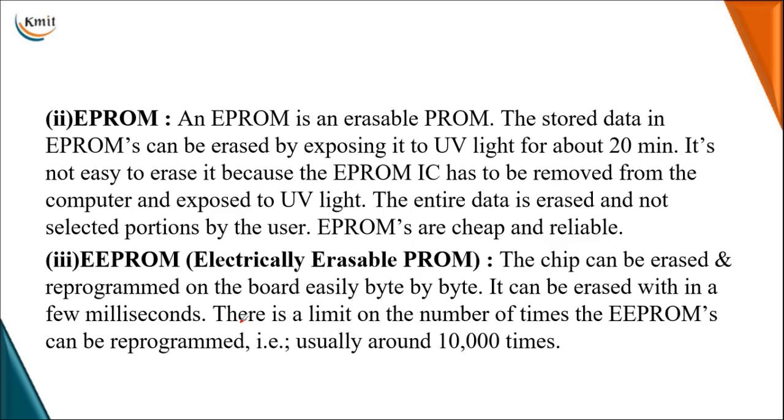But here a selective portion of your memory can be erased by selecting your memory location and passing electrical signals through a special pin. Then it will take a few milliseconds to erase completely. That erasing technique is limited to a number of times. Generally you can erase and reprogram it 10,000 times.